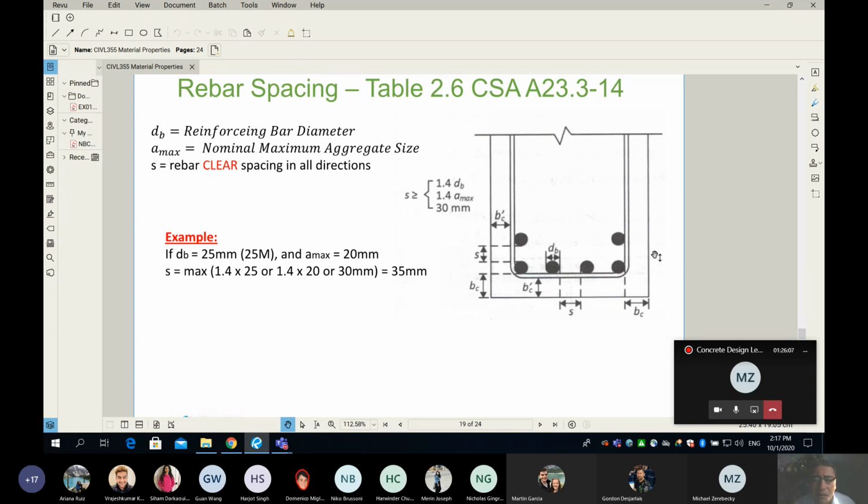But for example, if you think about a bridge girder, where the span is 40 or 50 meters, in this case we need lots of rebar, and the spacing is not sufficient. So what we do is we simply group them, we bundle them. But I will mention something kind of advanced for you guys.